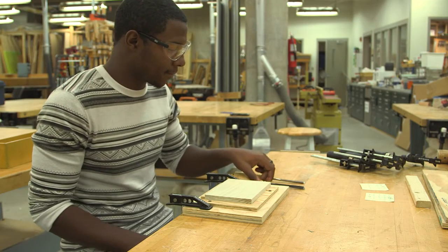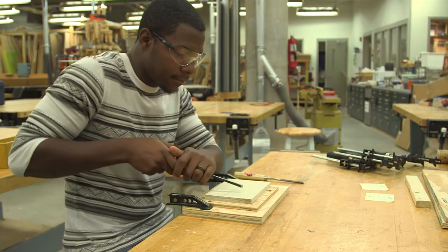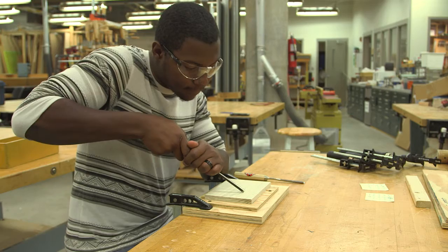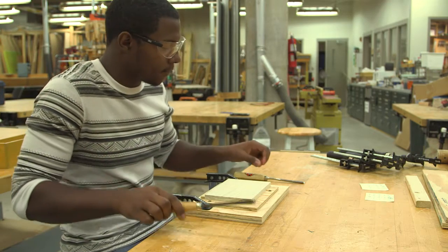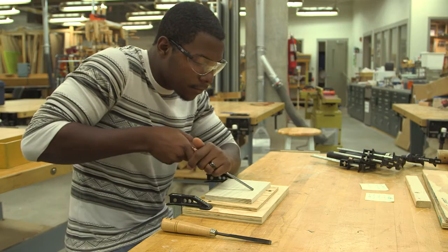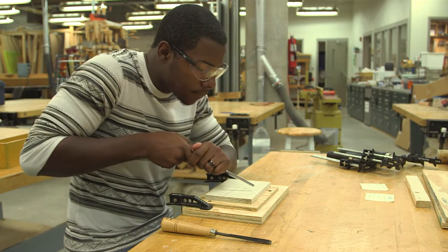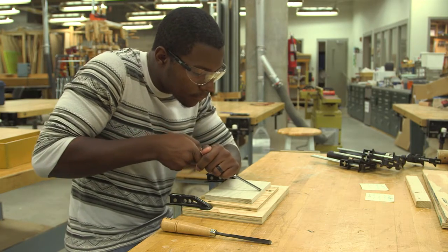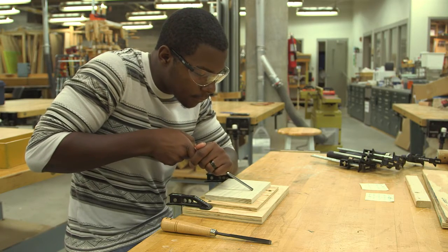The wood you are working on will tell you if the tool isn't sharp enough. If it seems that you have to apply too much pressure or force with the mallet to achieve a clean cut, the tool probably needs to be sharpened. It should cut easily, and you shouldn't need to fight the wood.